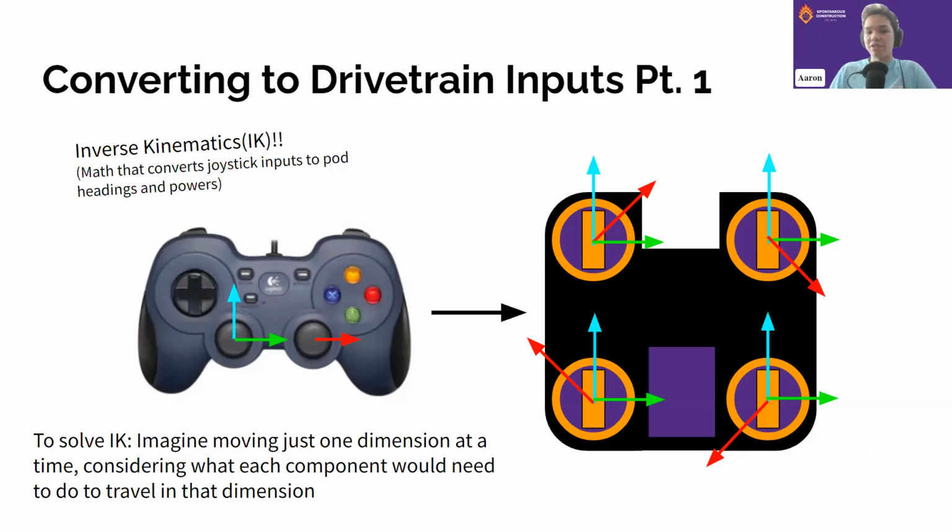But with a game like Ultimate Goal, you have launchers that use flywheels to spin it up, and doing flywheels with servos is not something that I think would be realistic, or at least not easy. So if the game has scoring that would be a lot more efficient with motors, maybe go with a 2-pod or go with coaxial, that kind of thing.